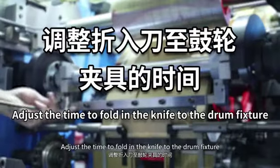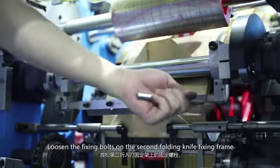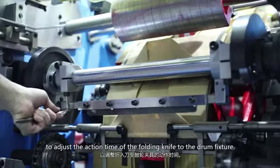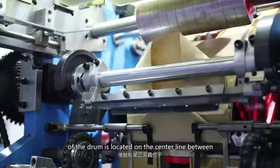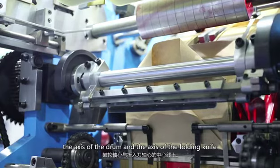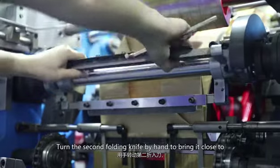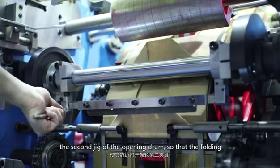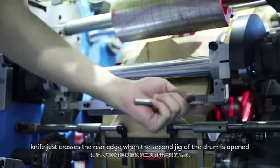Adjust the time of the folding knife's action to the drum fixture. Loosen the fixing bolts on the second folding knife fixing frame to adjust the action time of the folding knife to the drum fixture. Rotate the machine slowly so that the second clamp of the drum is located on the center line between the axis of the drum and the axis of the folding knife. Turn the second folding knife by hand to bring it close to the second jig of the drum so that the folding knife just crosses the rear edge when the second jig of the drum is opened.